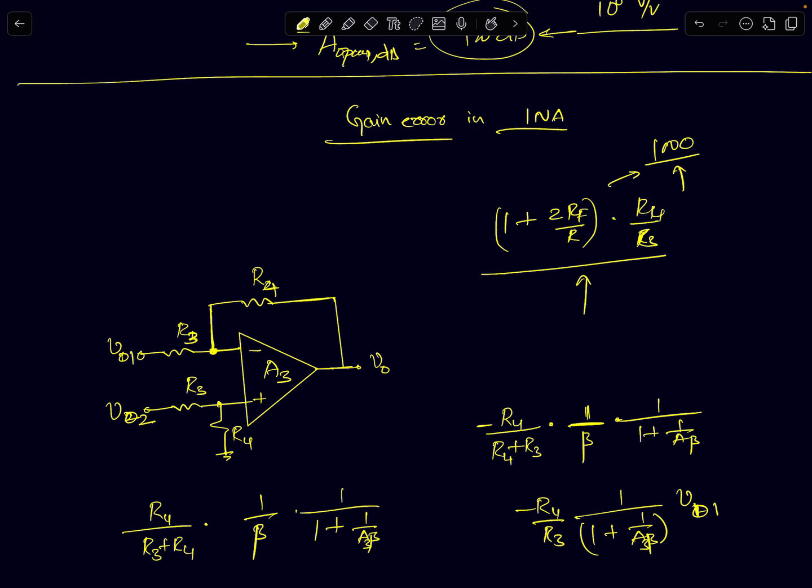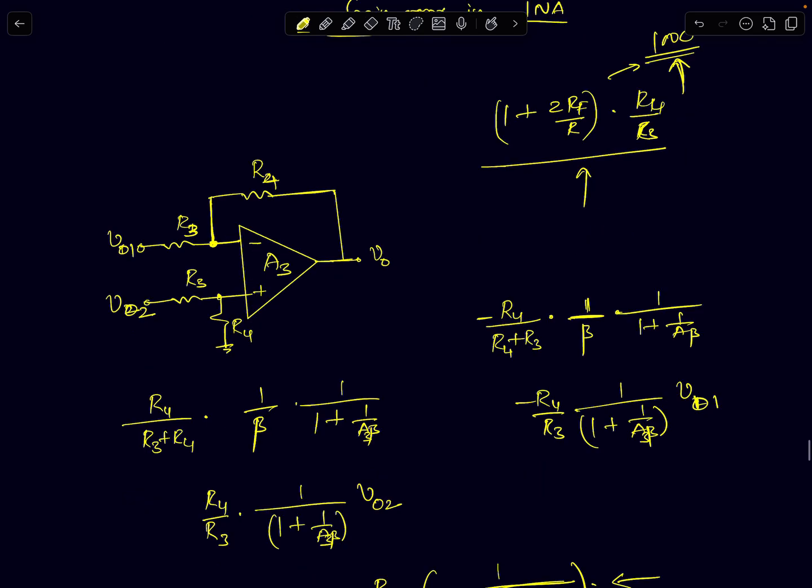If you recall, that is how we began talking about feedback, right? We said gain errors can lead to saturation or noise amplification in cascaded amplifiers, when we were talking about the telephone amplifiers. So that's one big problem. So let's say we want very high gain accuracy, then what determines the accuracy of gains? Like in any op-amp based circuit, the gain accuracy will be mainly determined by the op-amp's DC gains. So let's start with a simpler circuit, which is your subtractor.